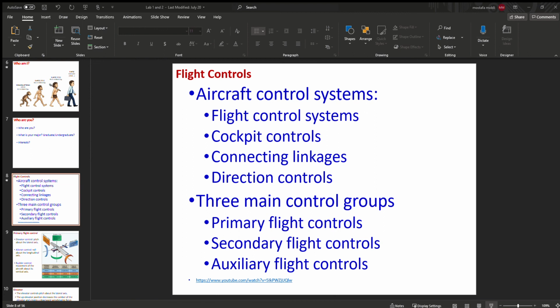Yeah, you can see the stick here. You can see actually a visualization here that we have turned the sticks to the right. You will have an upward deflection of the ailerons here, a downward deflection of the ailerons here. The downward deflection is going to produce more lift, as I mentioned, and also more drag, and we will talk about this. So the added drag,